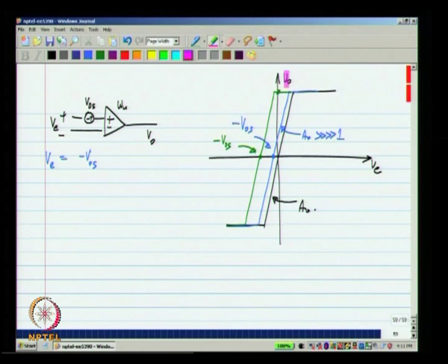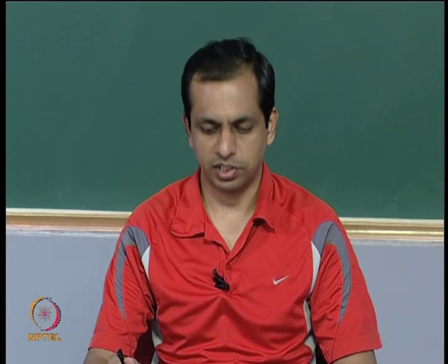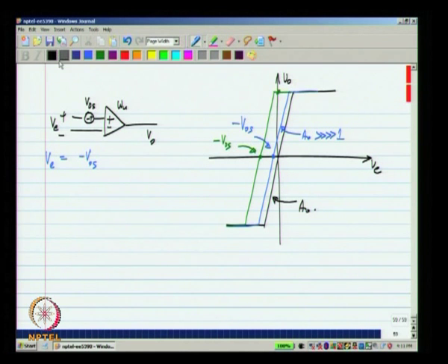This is not because the offset voltage itself is very large, this is because the gain can be extremely large. This curve is drawn with a modest slope, because I have to show the characteristics, but if I plot Vo and VE on the same scale, the characteristic of the op amp looks something like this.